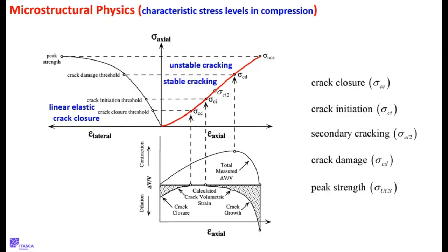One of them forms, and then another one forms a little further away, and then another one forms. And they're basically all isolated. So during this stage, from this strain to this strain, you got damage happening with cracks, but you could still unload this thing. It can still carry load. But it's damaged. It has all these cracks in it.